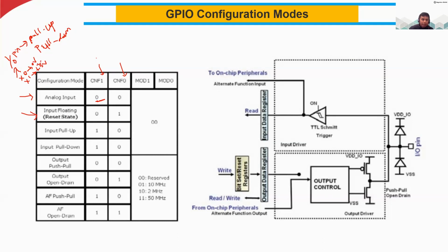Maybe it's about 0.8 volt, and suddenly it will go down to 0.6 volt, and then suddenly it will go up to 1 volt. So it will just keep changing. It will just keep floating. So in that kind of situation, we need to control this kind of pin. Then we have to use these pull up or pull down resistors, and then we have to apply the voltage, either make this pin 0, logic low, or pull it up to 5 volt level.